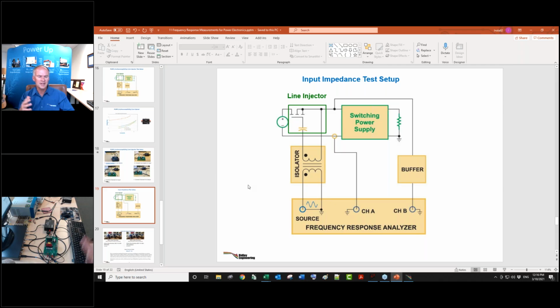You've probably got 30 different network analyzers out there. Okay, avoid some of them because they're just play kits basically. They're Digilent. You buy this box for $300 and you get 50 wires to hook up. So you have to build your own frequency response analyzer. So we did that. We got a measurement and then we put 5 volts on it instead of 3.3, and we didn't have a Digilent anymore. So that's not so good.